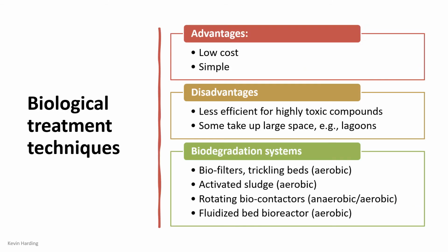Okay. In terms of what the treatment techniques are, the advantage of this is that it's low cost and fairly simple. So if you've got the system going, you can simply let it run and nothing needs to get added. You're not adding any chemicals to it. You're not taking any chemicals out. The microorganisms are the little mini factories on their cells, and they can do it at low cost and it's simple. Unfortunately, some of the disadvantages mean that it's less effective for highly toxic compounds. So where we would need some chemicals to try and neutralize it, it's less effective than those.